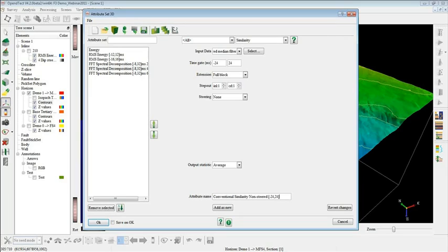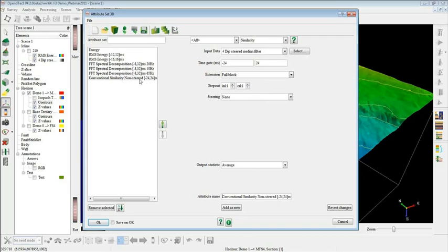Right, this parameter is very important. You need to provide the attribute parameter in the name so that when you're going to use it in future, you should know what parameters it has in there. That's why for each attribute I'm putting its parameter. And next I'm going to create full steer, which is going to use steering cube detailed.